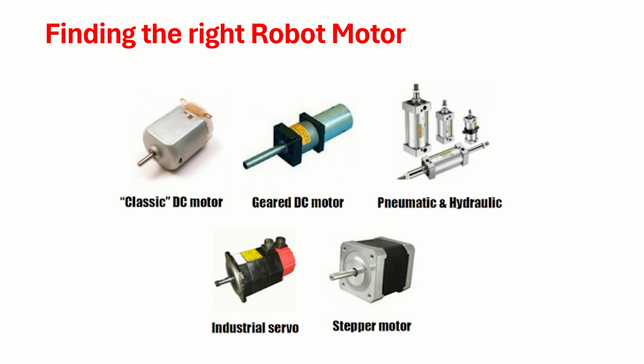Sometimes you also have some issues. The issues are their size and their weight. Say, for example, if you are planning for a moving object, a moving robot, then you also have a problem of the motor's size and weight, because that itself will become a constraint for you. They are heavy in terms of their dimensions and weight. Then, for a moving object, lifting the motors itself will become a challenge.